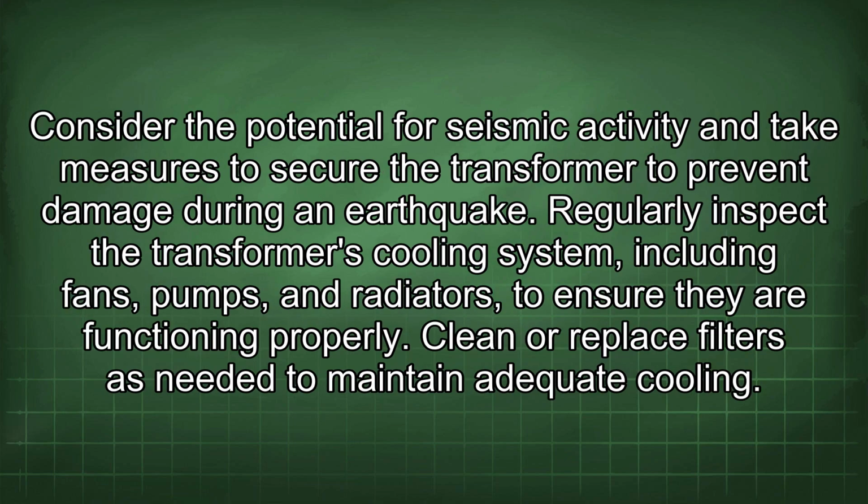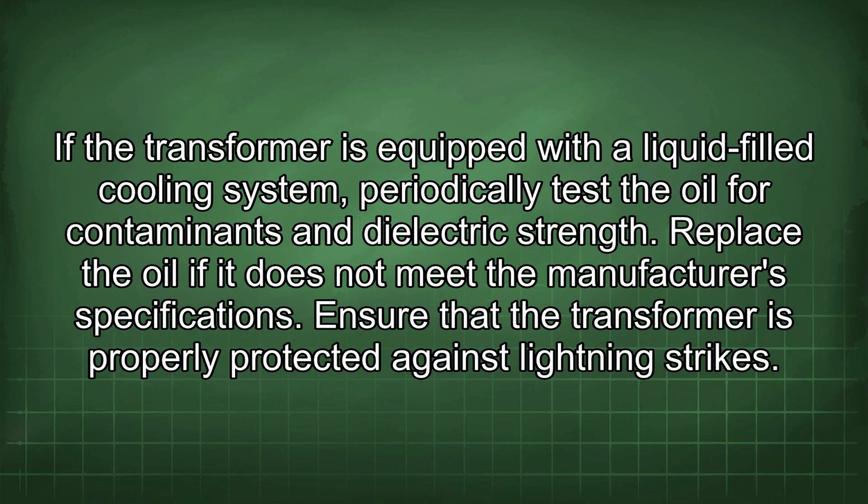Consider the potential for seismic activity and take measures to secure the transformer to prevent damage during an earthquake. Regularly inspect the transformer's cooling system, including fans, pumps, and radiators, to ensure they are functioning properly. Clean or replace filters as needed to maintain adequate cooling. If the transformer is equipped with a liquid-filled cooling system, periodically test the oil for contaminants and dielectric strength. Replace the oil if it does not meet the manufacturer's specifications.